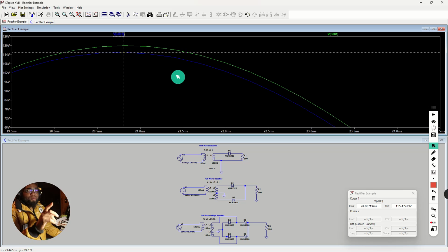Of course, these things are negligible, and you have to remember the caveat to this, which Stan didn't mention, but I thought that he should have: the circuit that he showed you in the book and the circuit I'm showing you now doesn't have any filtering capacitors on it. The filtering capacitors are usually going to up your voltage significantly, up to like 15 to 30 volts.